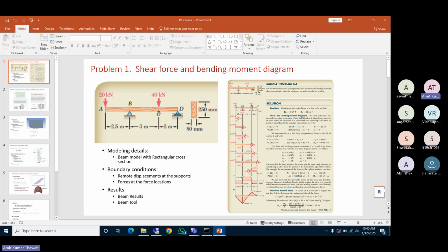In beams, we calculate the shear force along the cross section and the bending moment acting. These are the first force and moment calculations. Based on them, we obtain the stresses like bending stresses. So we will calculate the shear force, bending moment, and then the bending stress.